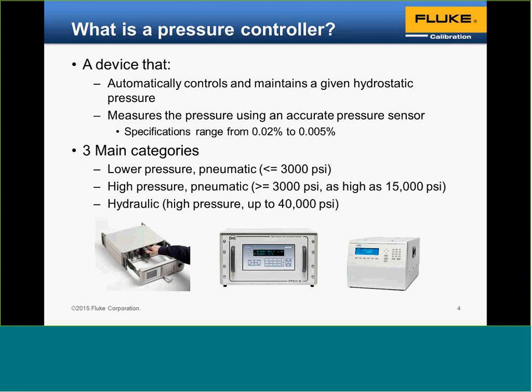So in our break-off points, lower pressure pneumatic, making up the biggest population, is 20 megapascal or 200 bar, 3,000 psi and below. The high pressure pneumatic is greater than 3,000 psi, 20 megapascal, 200 bar, as high as 15,000 psi. And the high pressures are up to 40,000 psi, or about 280 megapascal.